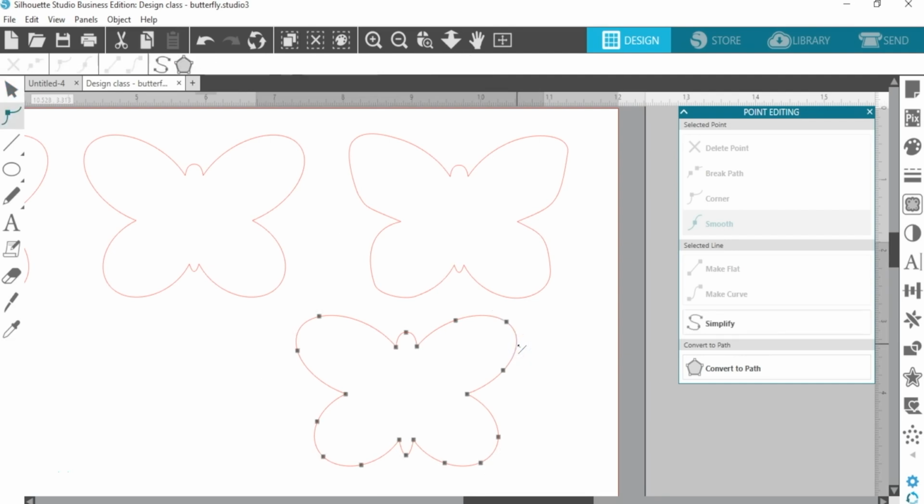Double-click the shape to enter point edit mode, and then drag individual points, or add more points if you want, and change the curve to however we want it. Just do what looks good, and remember you can change points and curves to corner or smooth as necessary, and manipulate the curves through the Bezier handles. This is just nice to play with and manipulate it to what works best for you.